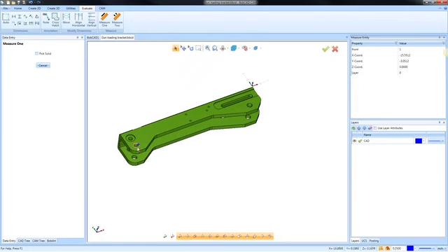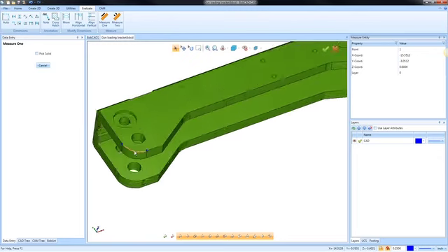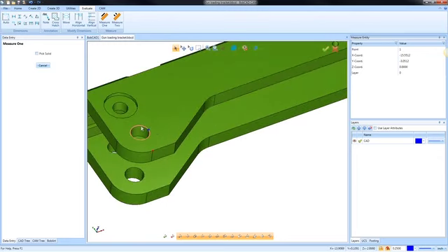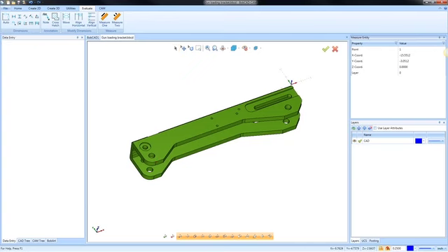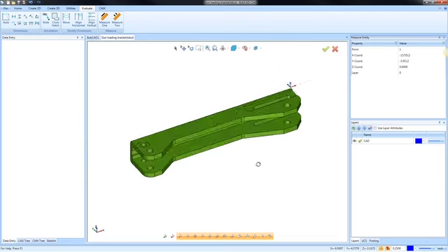But what if you want to define the center of this circle here? You can see when I move my mouse over it, it doesn't find the center of the circle, right? So this is one of the reasons why you may want to convert to wireframe, which is the lead-in. That's my next topic. We measured off the model directly. Now we may want to convert to wireframe, and we may use that for boundaries. We may use it for measurements.